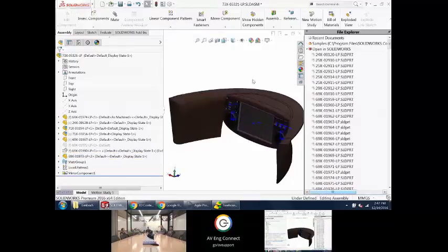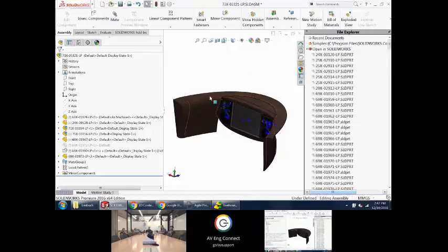Probably a good idea to do that and then just fix it. Yeah, that's also another way to do it. If you are worried about mate speed, again, depending on how your structure is, if you have nothing but a flat structure for your entire assembly, yes, do that. But if you've got sub-assemblies, you start hiding that stuff because a sub-assembly is rigid. It's not solving for that anyways. Sure.